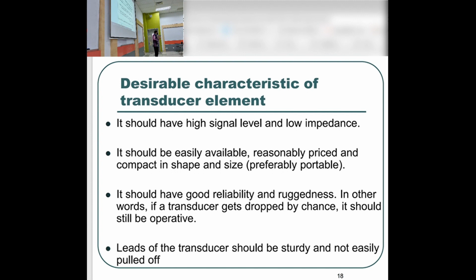So the thermometer is mechanical, and I think most pressure sensors, pressure gauges and pressure transducers are just mechanical. If you see in chemical plants, oil and gas plants, they frequently use a mechanical pressure transducer, which shows the reading using a needle as a display.